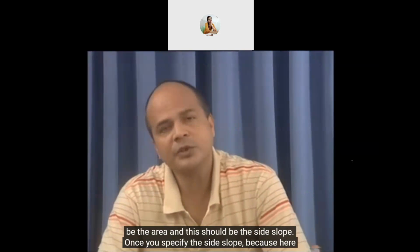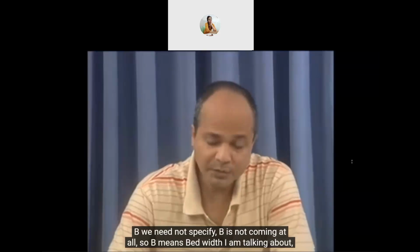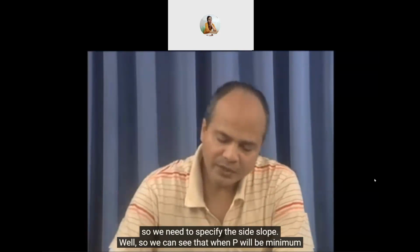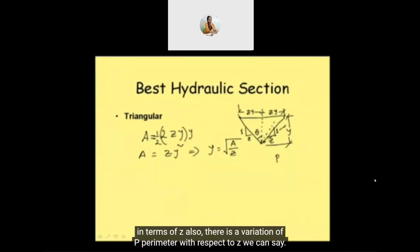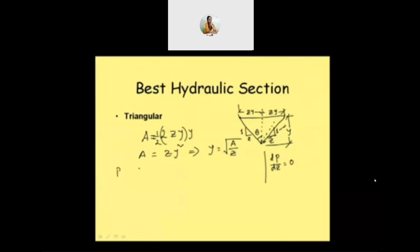Once we specify the side slope, B we need not specify, B is not coming at all. So B means bed width I am talking about. So we need to specify the side slope. We can see that when P will be minimum in terms of Z also, there is a variation of perimeter P with respect to Z. So we can try to find dP/dZ, and equate this to 0. So let us see what is the expression for perimeter P.